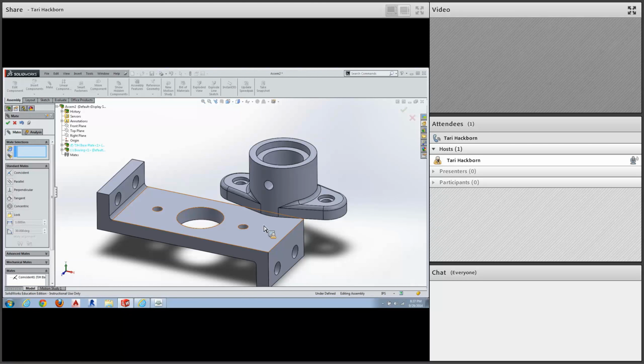So on page 13-14 and 13-15, we will be applying the second mate. Step 1, applying the second mate, says to turn on the temporary axis. Okay, that would be, which one of these? Temporary, okay. Now we have our temporary axes. And we are in the mates tool yet. So I will select this axis right here. There we go. And this axis. Come on, turn yellow.